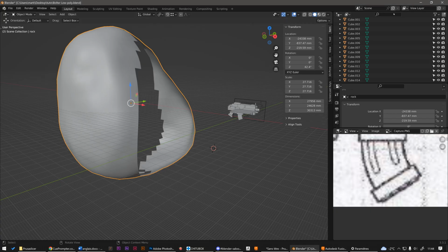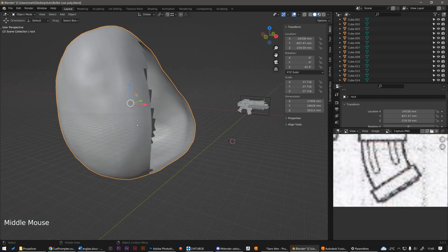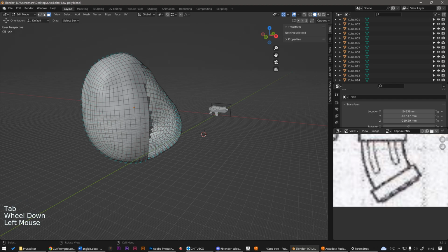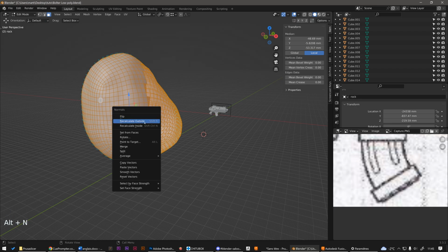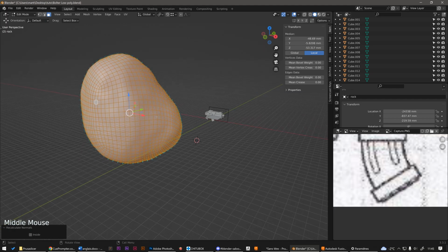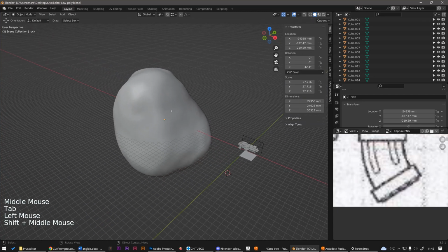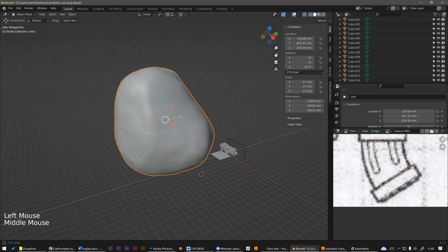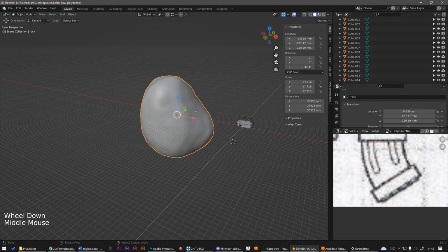Blender has a tool that allows us to make all normals uniform, that is to say, to orient all normals either inward or outward from the volume of an object. So I go into Edit mode, I select all the rock faces with the A key, I display the Normals menu with Alt+N, and here we find this tool called Recalculate Outside, and voila, all the normals are now facing outwards, and our object has again a kind of consistency, and it will be able to be printed without any problem. So that's one of the fundamental functions of normals, being used by the engine to calculate faces visibility. And that's it for the theory.